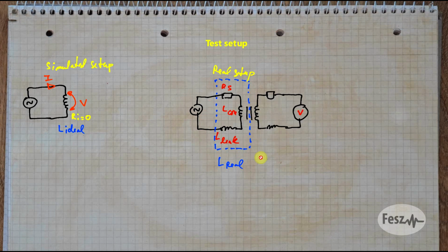So in the interest of better accuracy, a better way of performing this measurement is to use a secondary winding to observe the voltage present on the part of the inductor that is coupled to the magnetic core. As long as the secondary side is connected to a large enough impedance, any losses present in the secondary circuit, so from the series parasitic elements, can be neglected. And well, for the current, with or without the various parasitics, the current in the coil of interest is the same. So if we measure it between the signal source and the coil, it should be just fine.